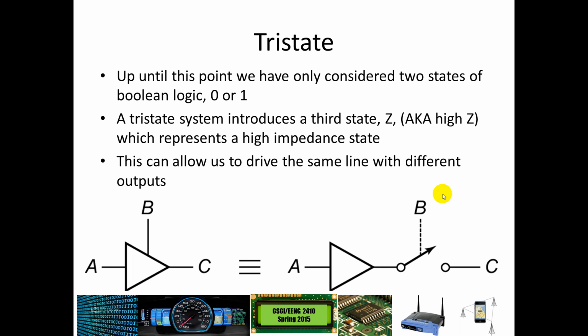In some cases, you may want to not necessarily connect that device all the time, or you may want it to not really have control over whatever it happens to be connected to at a certain moment in time. And so in that case, what you want to do is have a tri-state, or third state, which is Z, a high impedance, and what that will allow us to do is basically get that device out of the way so that the other devices can come on through.